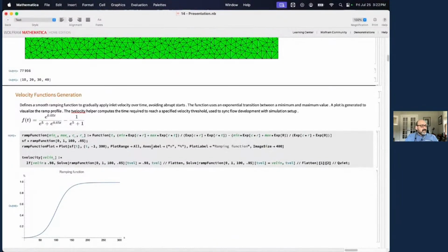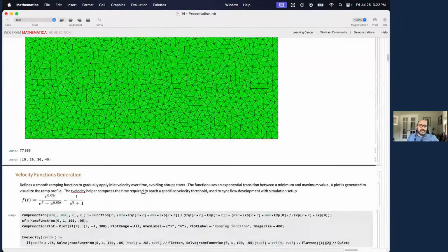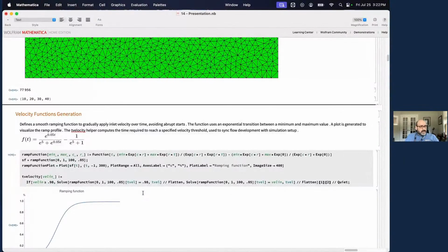Now, the Navier-Stokes equation is a very tricky equation. You have to ramp it up, and you see this through the PDE solution. You have to ramp up the functions. You cannot just give a solution; you have to start from zero and slowly ramp up. One of the other techniques I use to get this solved is this: when you try to solve the Navier-Stokes equation at higher velocity, you will introduce a lot of turbulence, which, again, is a problematic issue. At the surface, at the PDE interface between the surface and the air, it is basically a linear solution. You don't have to take this turbulence into consideration.